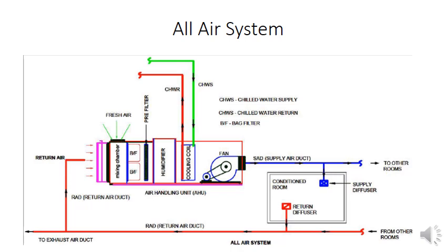This AHU consists of dampers, mixing chambers, filters, cooling and heating coils, dehumidifier, fan, blowers, etc. All this equipment is marked by the pink one, mixing chambers, filters, fan, cooling, heating, everything. This processed air is then supplied to the conditioned space, the blue one, through the SAD, supply air duct, which is known as the supply air distribution system. This also consists of ducts, dampers and diffusers.